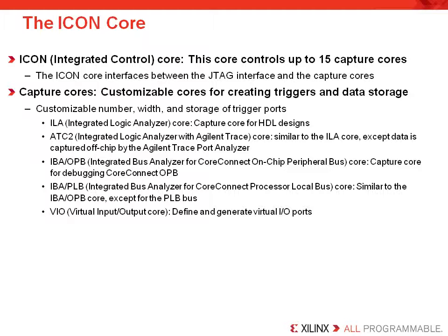The ILA is most frequently used for HDL designs. Each ILA core can be customized for the number and width of signals to be captured or triggered. The ILA core is the most commonly used capture core. The ILA and ICON core are supported with the inserter flow.